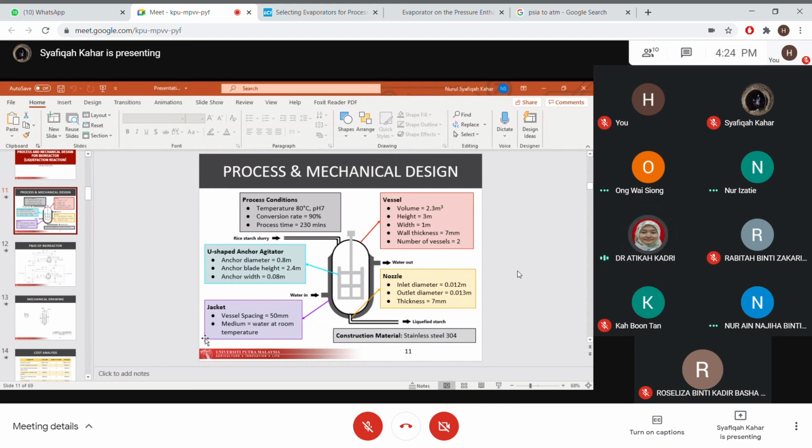Do you know what is the best position of this impeller against the bottom of your vessel? Best position, I believe, because there is no actual design that I really found through the internet on the anchor design. So I may assume 10% or 20% from the bottom of the tank.